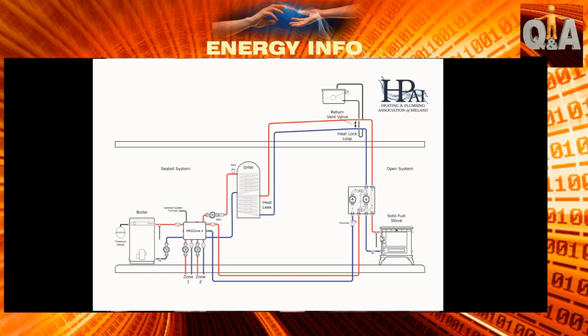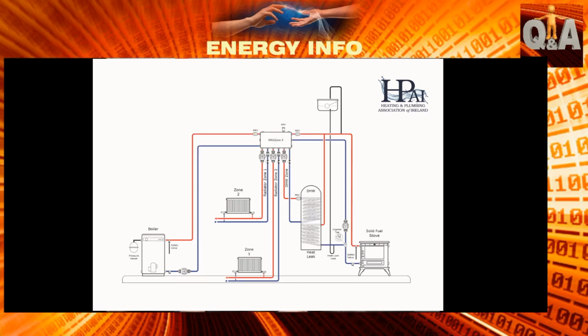Here again is a situation where you could have, say, a dual system. Again, we're not really focusing on the dual system aspect. But in this, if you follow the flow up, you see that it can pass through to your secondary system, secondary being your motorized valves or manifold or whatever. There's an open path for it to go down through the coil, and so that's a priority hot water situation where the stove has an open path to heat the water first.